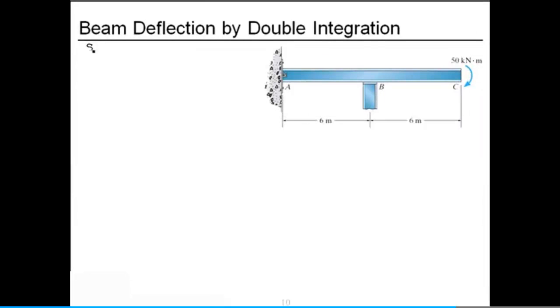We're now ready for step 7, which is to predict the vertical displacement at C using equation 4 with its constants determined. So we ultimately discovered that the vertical deflection in the range of x2, which runs from B to C, is given by minus 25 kilonewton meters over EI times x2 squared minus 100 kilonewton meters squared over EI times x2.